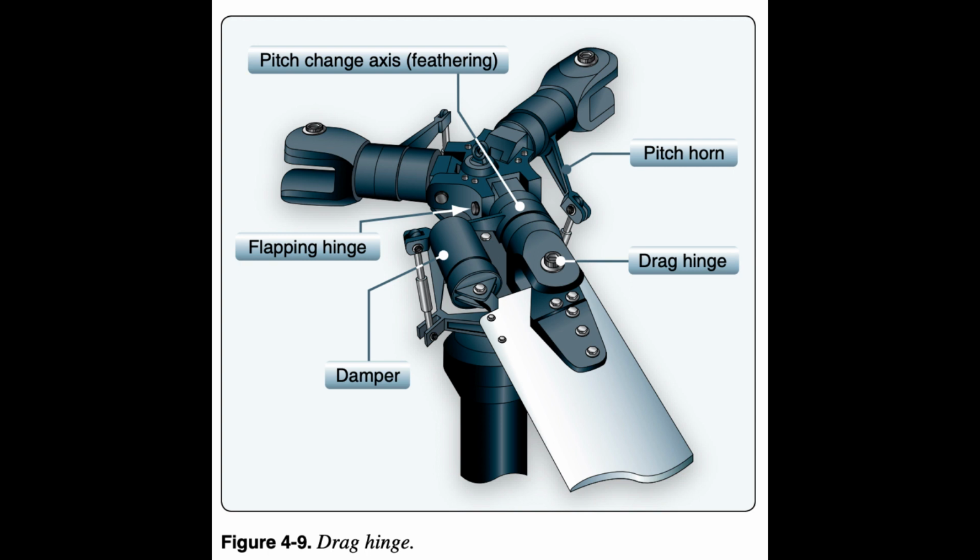At the lowest point of load, it is at its lowest flap angle and also at its most rearward lag position. Because the rotor is a large, rotating mass, it behaves somewhat like a gyroscope. The effect of this is that a control input is usually realized on the attached body at a position 90 degrees prior to the control input displacement in the axis of rotation. This is accounted for by the designers through placement of the control input to the rotor system so that a forward input of the cyclic control stick results in a nominally forward motion of the aircraft. The effect is made transparent to the pilot.